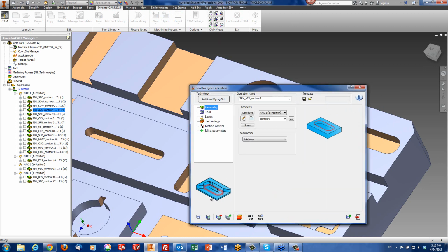If we take a look at the diagram on our left hand side on the bottom, you can see this is the actual tool path that's going to happen. It's going to go down zigzag until its first step down, work its way across, and then go down again and work its way back. When it finishes that, then it'll work towards the sides parallel to the geometry itself. The direction of the chain that we create over here does not make a difference.